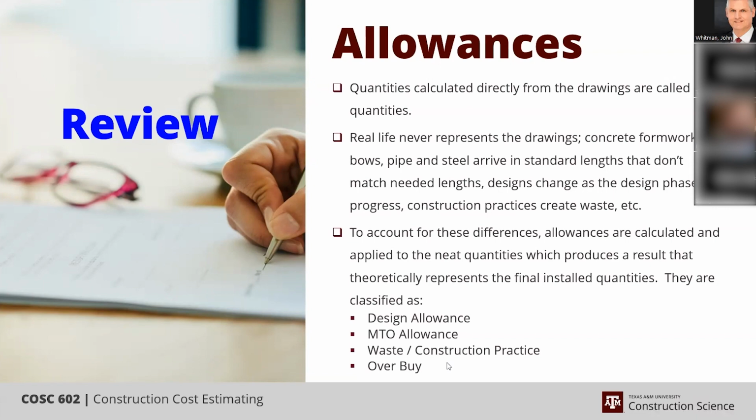In the estimate template itself, you'll notice that each one of the columns in the detail section has a built-in column for ratioing and adding allowances and so forth, and that would be where you'd put the actual design allowance for the equipment and for the instrumentation, because normally as far as quantity is concerned, there's not near as much fluctuation in instrumentation quantity that they may find as things progress a few more places they need an instrument to monitor flow or vibration or something they didn't account for.